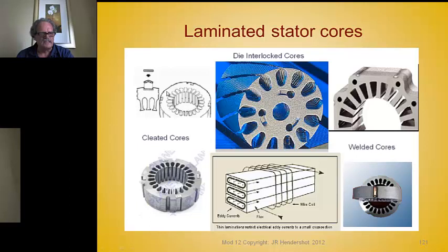This is a pleated core. There's a notch punched in the OD, and then this steel cleat. They're stacked on tooling and arbors, and then this cleat is forced in there and kind of flattened with wedges itself and holds the thing together.